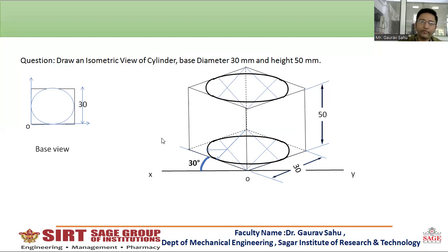You have to draw it very finely because these kinds of gaps will always arise in certain questions, so try to avoid these kinds of joinings. You have drawn the top circle and base circle. Now draw the vertical lines joining the sides. Now our cylinder is completed, but a cylinder is incomplete until you draw the generators.